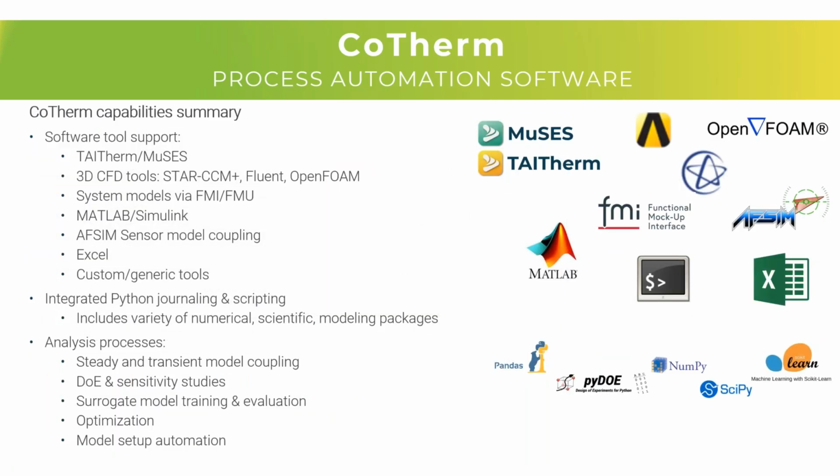This slide just briefly summarizes some of the different tools and capabilities that CoTherm has. In terms of software tools, we of course tightly integrate with our own thermal software, so CoTherm or Musis on the defense side. It works with several 3D CFD tools with native integrations for StarCCM+, Fluent, and OpenFOAM, and other tools as well. It works with system models via either the Open FMI interface standard or natively with the MATLAB Simulink environment. We also work with a number of engineering productivity tools, Excel, and so on, and other custom tools